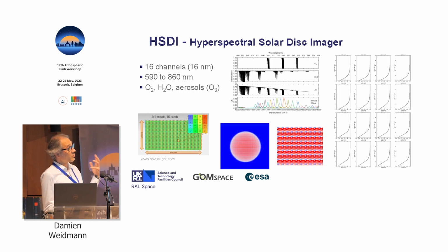Now, since we're using this type of imager, why not try to get scientific data out of it too, by making it a hyperspectral imager? To do that, we're using a mosaic of filters, which is directly deposited on the focal plane array of the sensor. If you look at the focal plane array, you actually have a 4 by 4 little mosaic, which means that from a full high definition image, you can split it into 16 low resolution images, each with a very specific filter response.